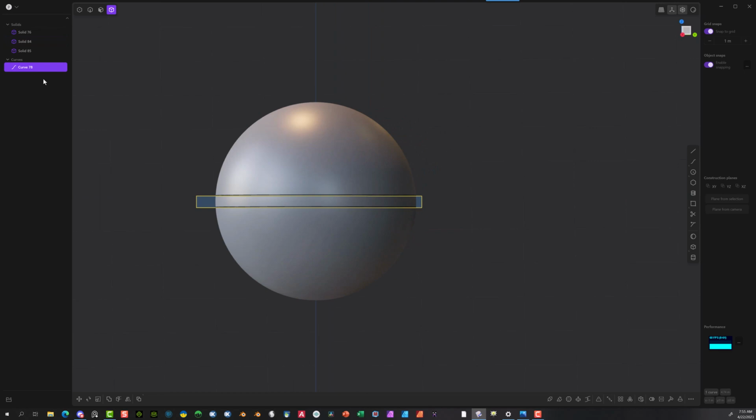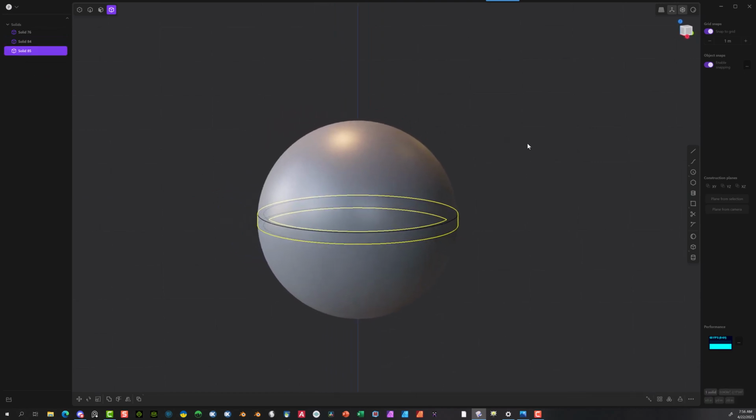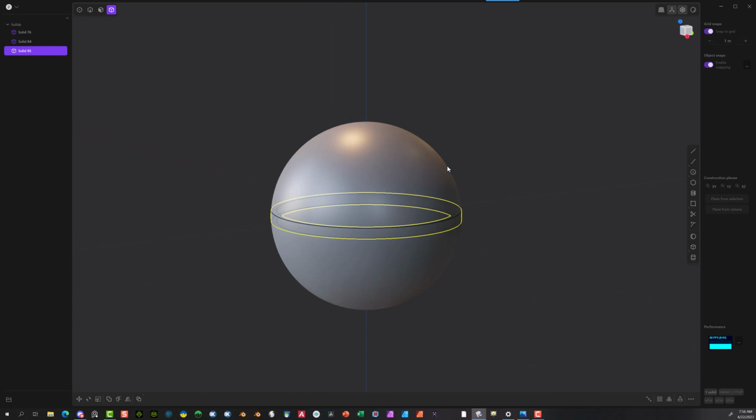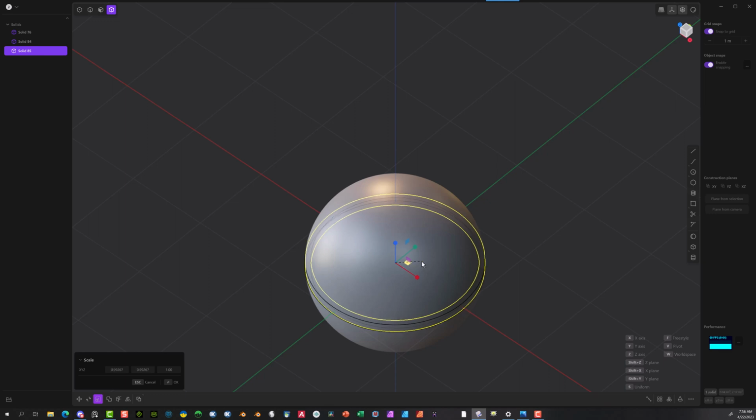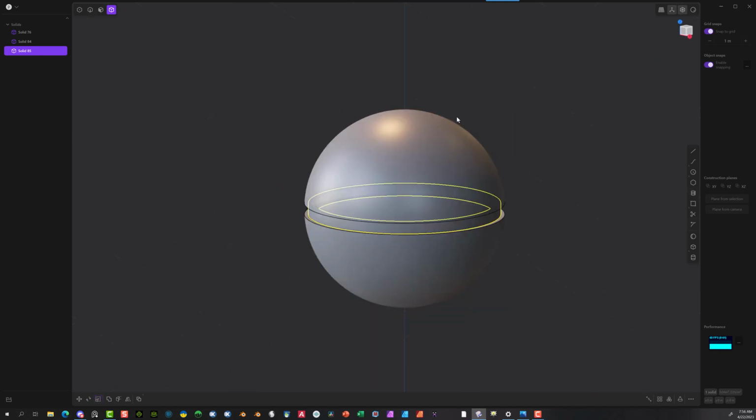So now let's go ahead and get rid of the curve, delete this, select this section in the center here, and we're going to scale this down. So we're going to hit the S key, and one thing we can do is we can select this right here, bring it in, drop it. I'm going to put this at 0.96. Again here, same thing, 0.96, so it's even throughout. Say OK. Okay, so there's that.